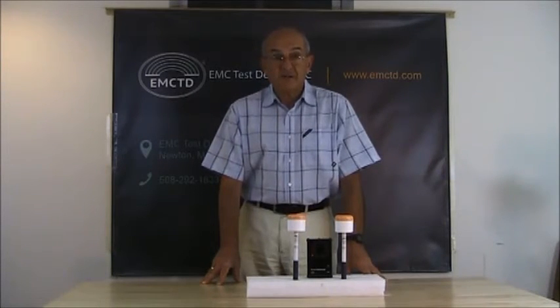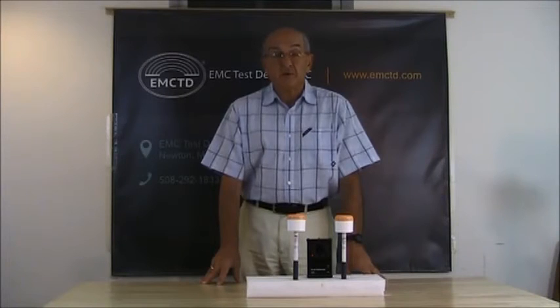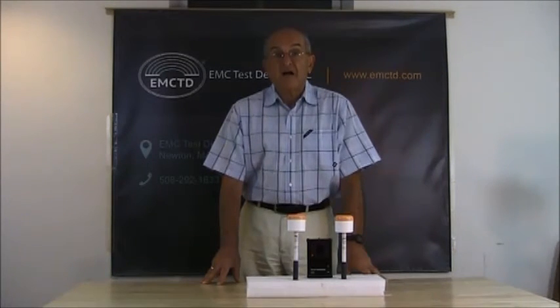Because the output of the probe is proportional to the power density, if you have multiple sources, the output will be proportional to the sum of the power densities from all sources, and in order to assess RF safety, the operator does not need to know the frequency of each source. This probe is a very useful and quick tool to assess RF safety in any environment.